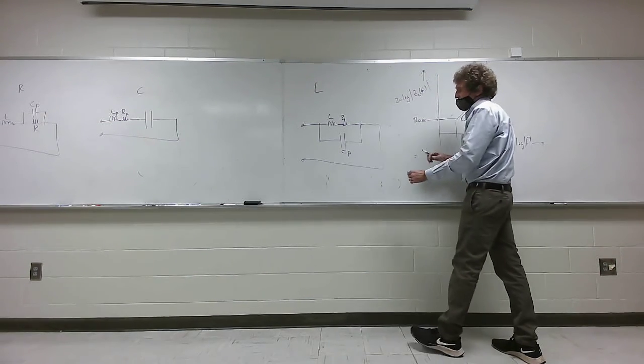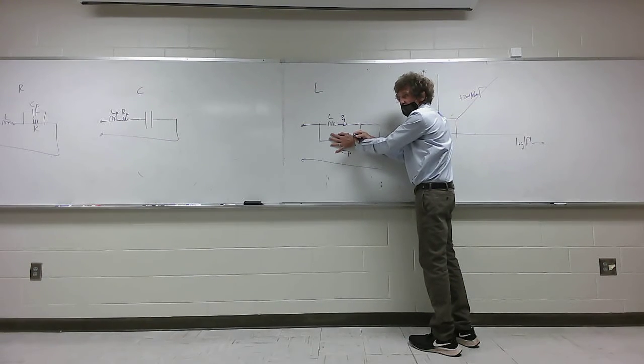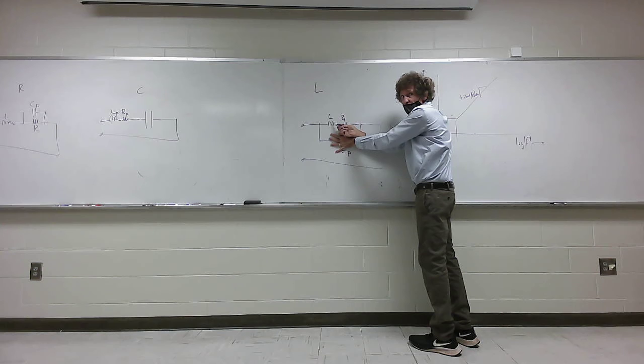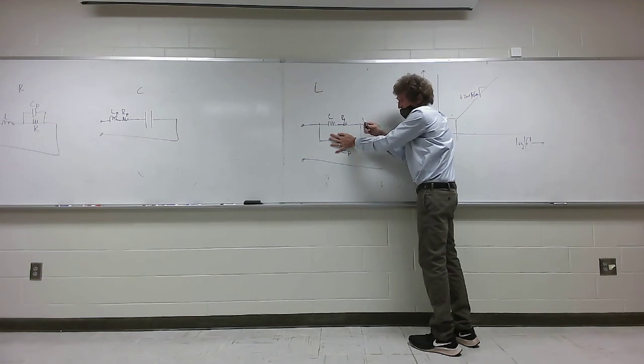All right, now what that is, forget this capacitor. If you just have an inductor and a resistor, I want you to just think about this. When all of a sudden the inductive reactance is equal to the resistance, the inductive reactance will start dominating after that frequency. That's how you get the first breakpoint, and I'll get to that in a second.